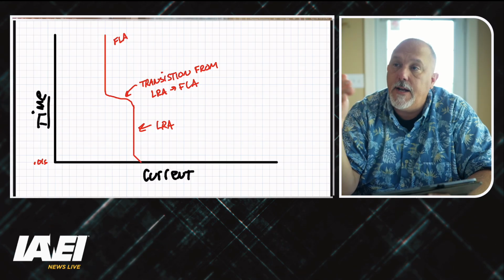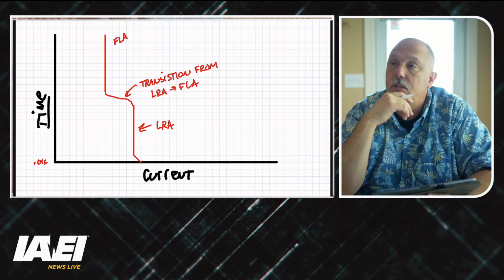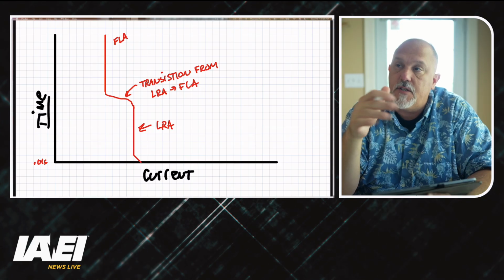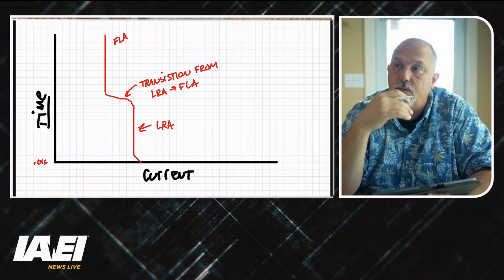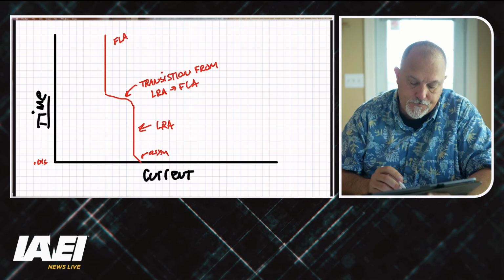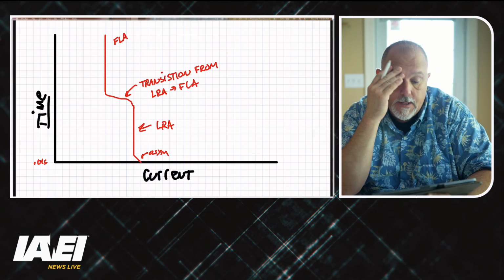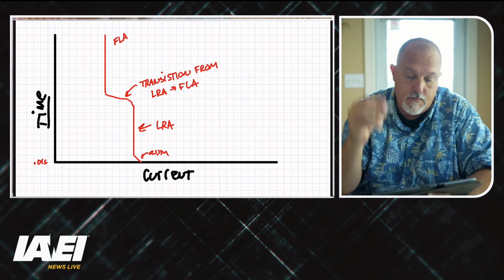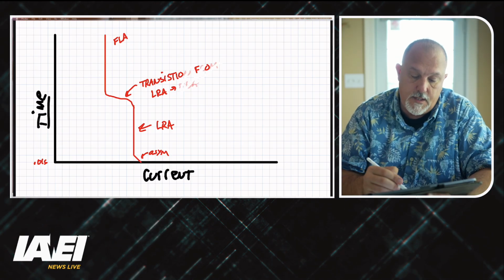So she basically establishes her start curve. She'll know her hot and cold stall times. She plots her symmetrical start curve, asymmetrical start curve. That's your asymmetrical. And then, after all of that, let's delete some of this.